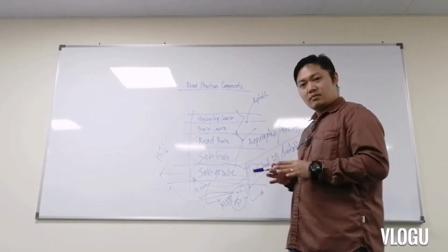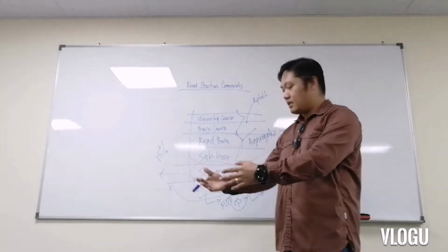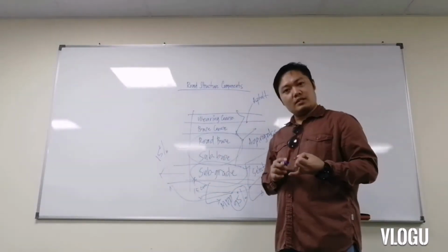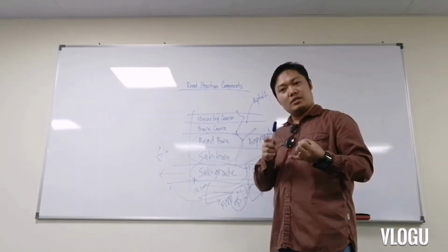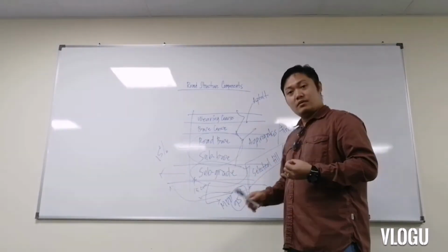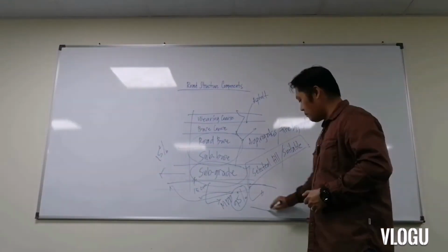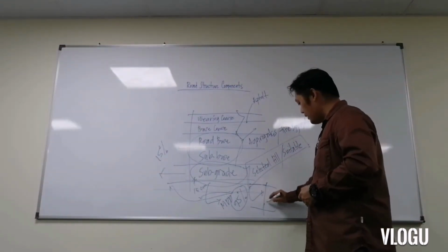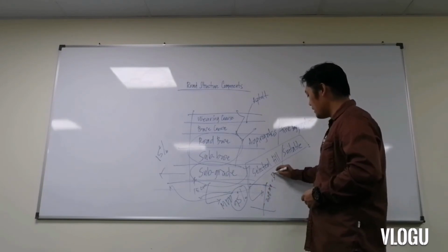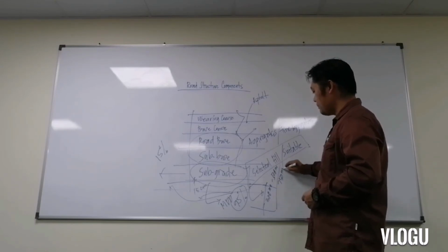So what are the tests for the subgrade before we proceed to the next layer of subbase? First we have to determine that all these are suitable. We have to ensure that the percentage of MDD has already passed in layers, because sometimes the thickness of this subgrade is normally between 300 mm to 500 mm, and sometimes it goes up to 750 mm.